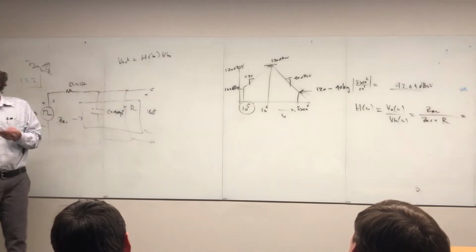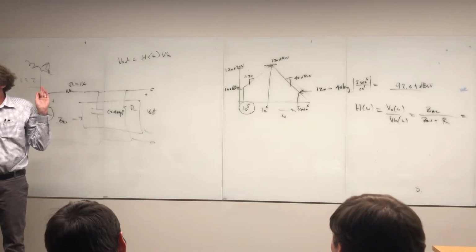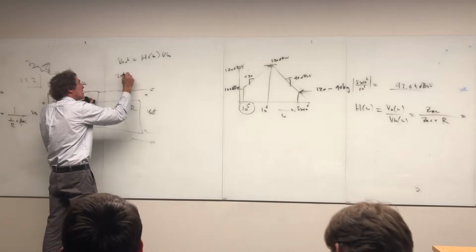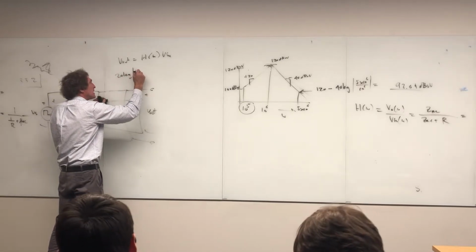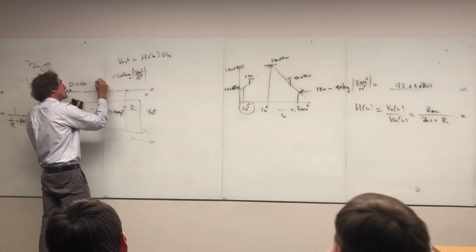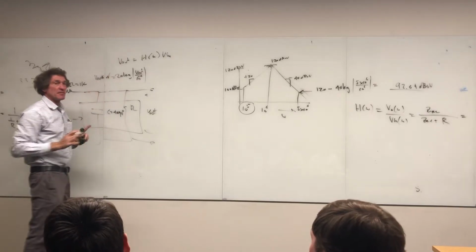Now, if we put this in terms of dB microvolts, because that's what our signal was given as, then you can see I would take 20 times the log of the magnitude of V out over 10 to the minus 6. Then this is going to be the output V out in dB microvolts, correct everyone?